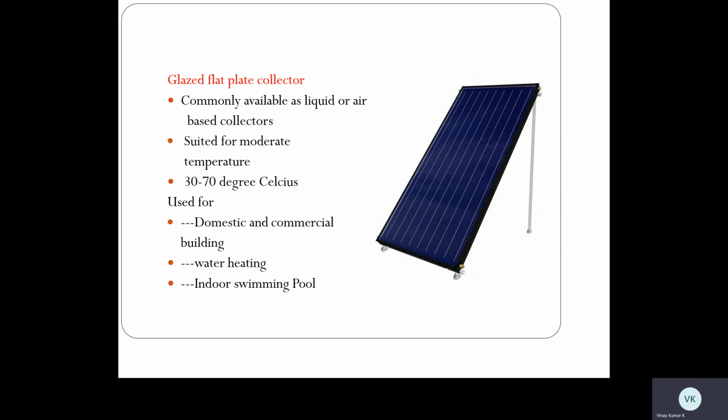These collectors are better suited for moderate temperature. That is, if the application is for moderate temperature, about 32 degrees Celsius, we can use glazed flat plate collectors. During the winter months mainly, solar collectors are used, and the liquid based collectors are most commonly used for the heating of domestic and commercial hot water.